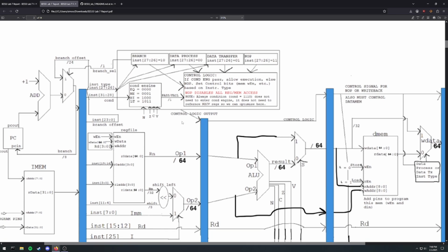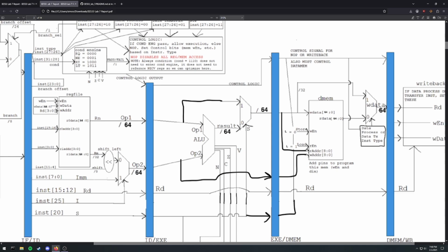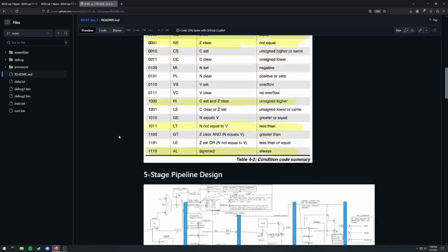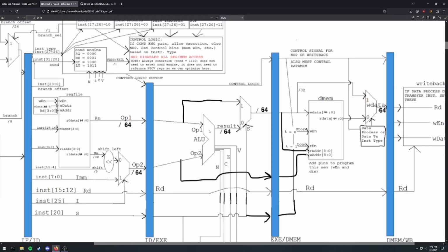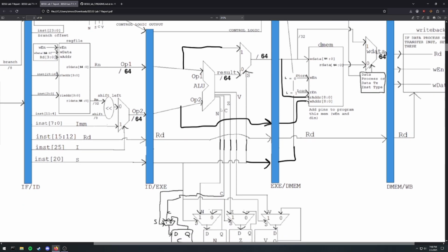It also determines the kind of logic control that gets inserted into the pipeline relative to that instruction, so it'll stay alongside that instruction. Our ALU just has to implement add, subtract, and compare, where compare does the subtract. So not too much going on there, and also updating the NZCV flags. Those are the outputs.